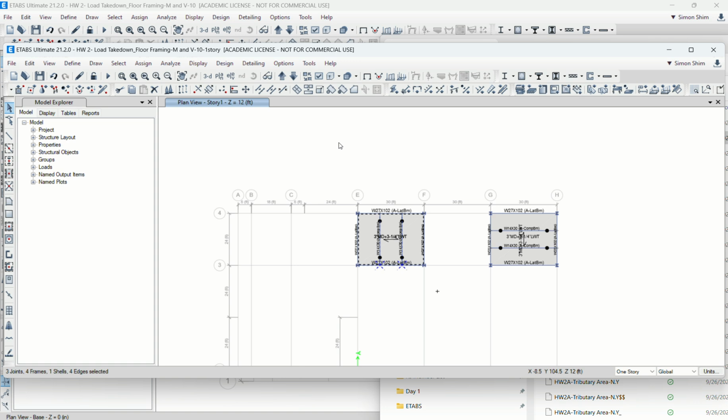Residential building: when you visit your house, measure your room size. Okay, living room size, look at it. What is the dimension? Residential is usually smaller than office space-wise, right? Your room might be maybe 15 by 15, plus or minus. But they don't need 40 or 45 feet span. Commercial office is typically a 30-foot column spacing, and this is about 40, 45 feet. We'll find out with some examples I will show you.